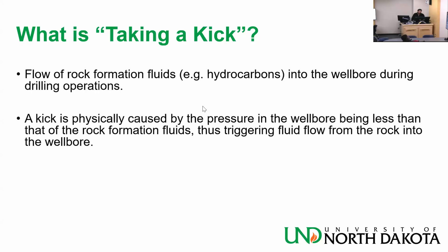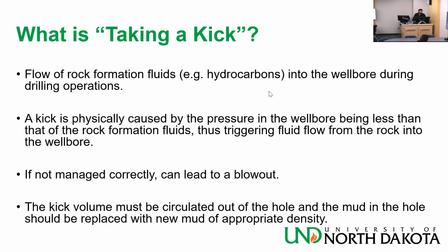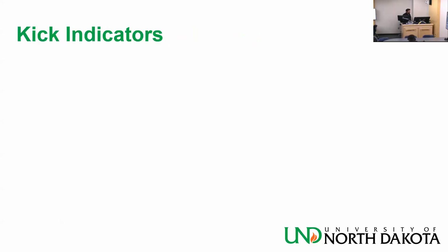A kick is physically caused by the pressure in the wellbore being less than that of the rock formation fluids, therefore triggering fluid flow from the rock into the wellbore. That's a kick. If not managed correctly, you're going to have a blowout. Boom. The kick volume must be circulated out of the hole, and the mud in the hole should be replaced with new mud of appropriate density. You get a kick because you are dealing with the wrong density, so you have to replace that.